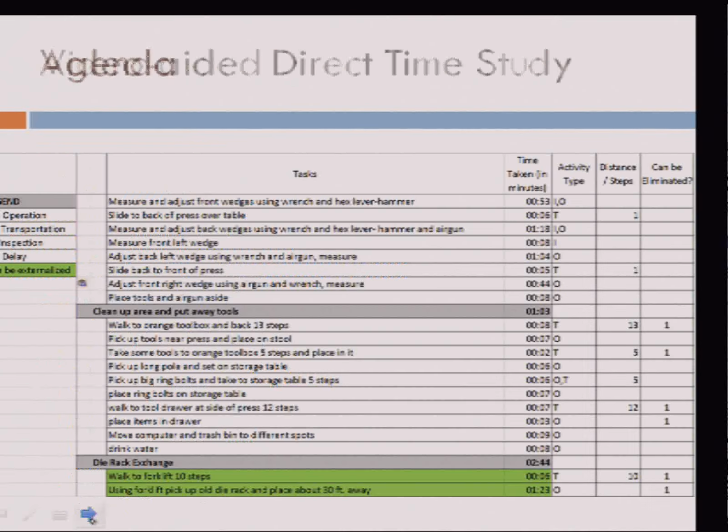So data collection, this is again the tedious part, and at that time we did not have access to time study software. Only today we know that there's at least a Workplace Planner from ProPlanner Inc., and there is a Timer Pro from Applied Computer Services, and then there are other commercial vendors of both process videotaping, and then from the videotape you can go to quick decomposition of the process into elements. So this is video aided direct time study.